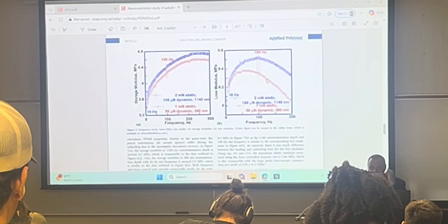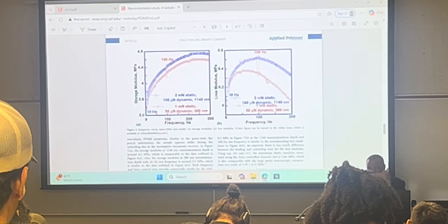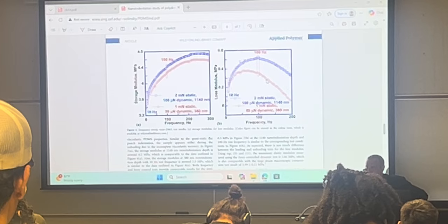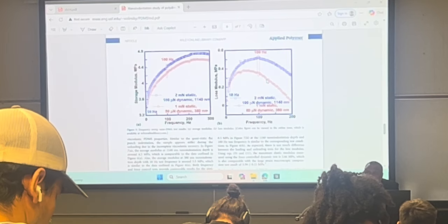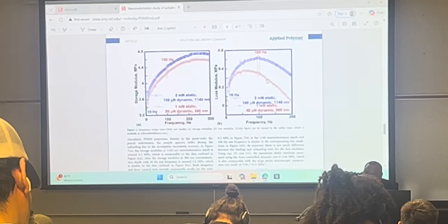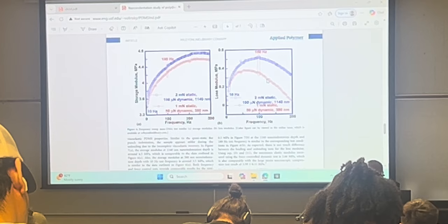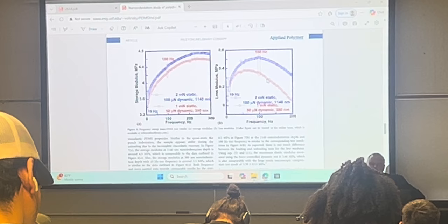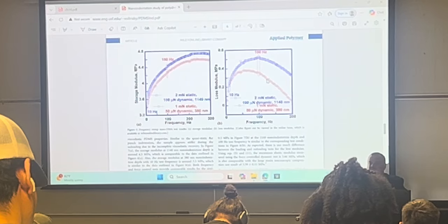So by doing this, you can feel the temperature differential. And I'm not sure exactly how much it is, but at least I would say maybe 1 degree. So what does that mean? It means that when you're testing the mechanical properties of polymers, it's not a simple tensile test, like that tensile machine I brought to the other class. It matters how fast you do it. So you're going to get different response if you do it fast versus if you do it slow.